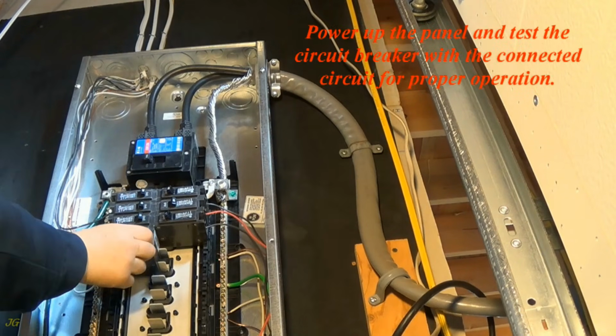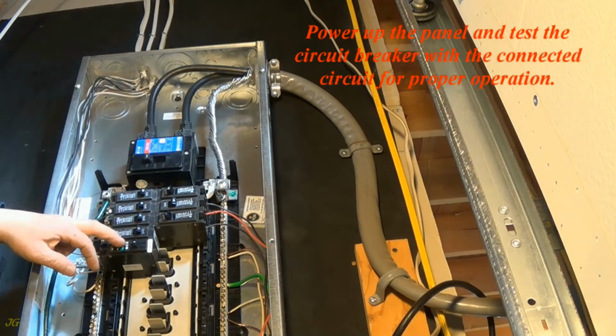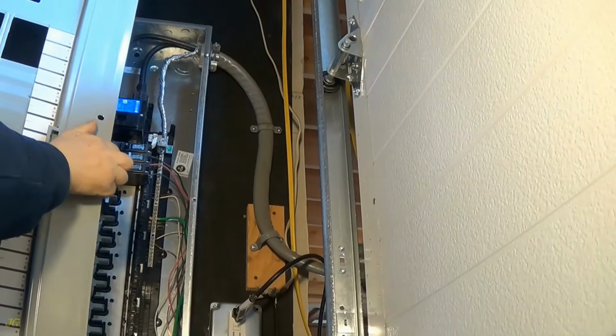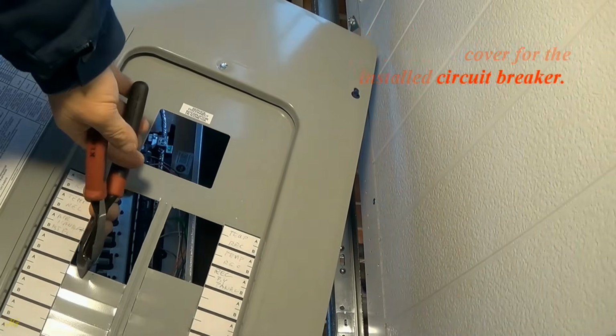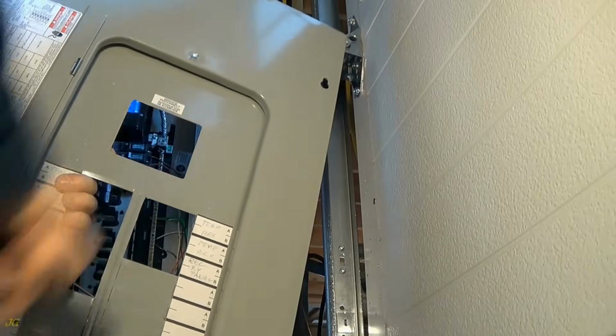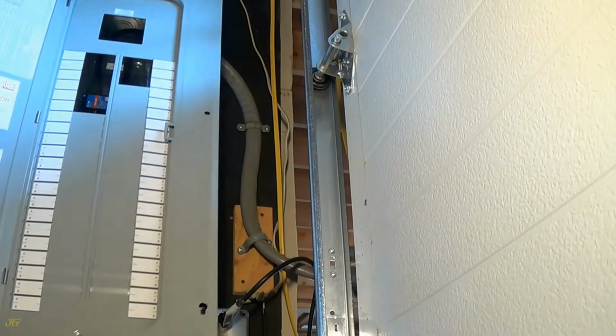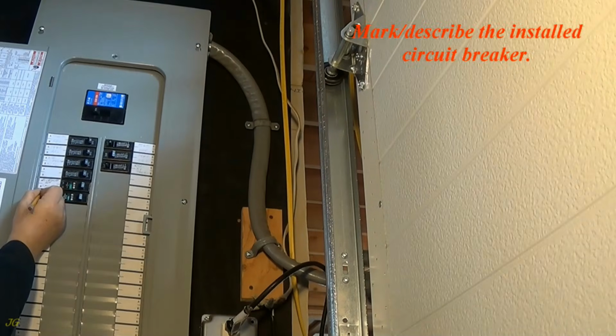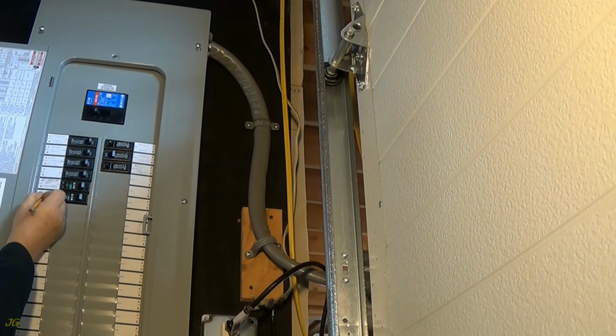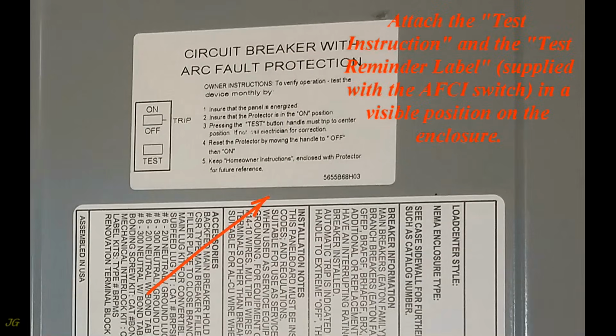Power up the panel and test the circuit breaker with the connected circuit for proper operation. Remove the knockout and panel board cover for the installed circuit breaker. Reinstall the panel board cover. Mark, describe the installed circuit breaker. Attach the test instruction and the test reminder label, supplied with the AFCI switch, in a visible position on the enclosure.